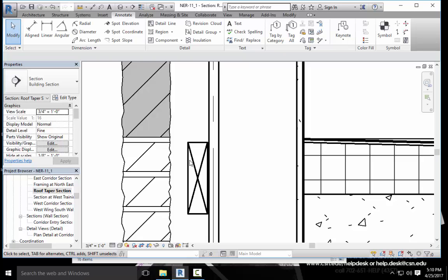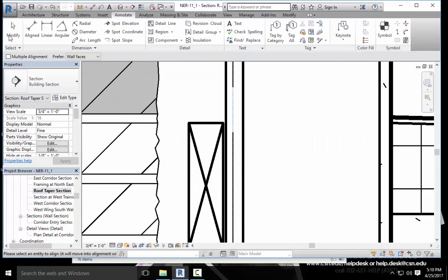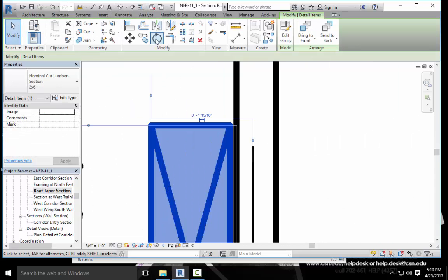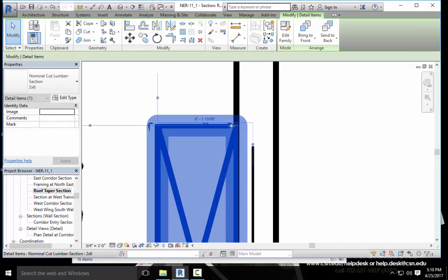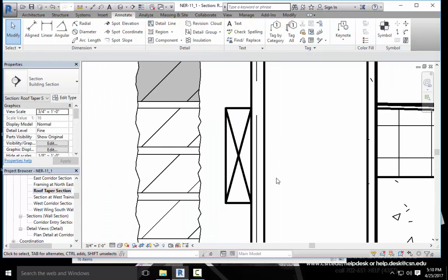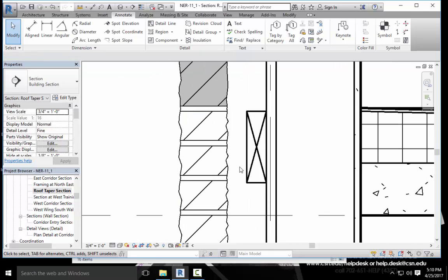The next step is to add the corrugated wall tie, but before we do that, you want to be really precise about how you do this, and gaps like that will come to kill you eventually. So we're going to take a little bit of time and just make sure that we move this to where it would actually sit. And if we want it aligned with that, then we're going to want to make sure that those two things are aligned, and they are. So if you're drawing a detail, you want to be very careful about how you're drawing it. Really, you want to be very careful about how you're drawing anything, but especially details, because those little mistakes, when you print them at a large scale, will actually show up.